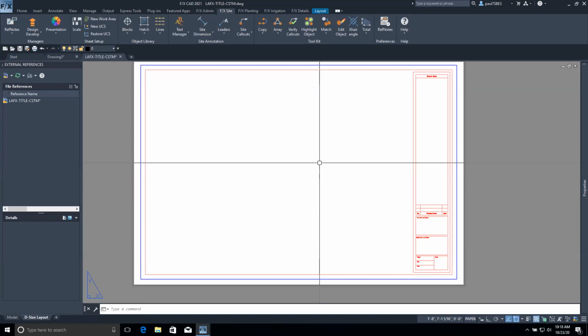It's basically, once you place it in the drawing, the block is defined in the drawing, and so you're good to go. The drawback is that if you're working with a lot of sheets and you want to make changes to that title block, you have to either edit the block definition within the drawing, or edit the source block, but then you have to open up each sheet that is referencing this block and redefine the block, which there's a command for called redefine block.